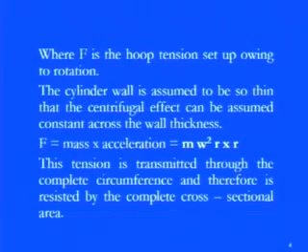So, this is nothing but equal to mass into acceleration, and if you consider the acceleration, that is omega square r, into r. If you multiply with the mass, we have m into a, that is the applied force. So, m omega square r into r, or we can say m omega square r square, and this is a tensile force.